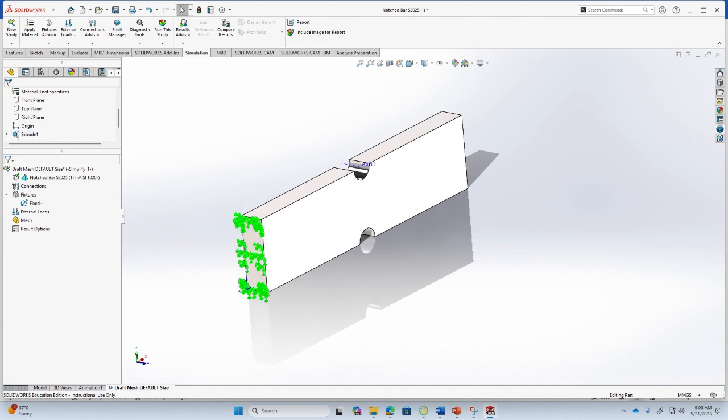And now these green arrows are showing you the constrained face, right? They are showing where the displacement is 0. So the way any finite element analysis applies these boundary conditions is that internally it writes this relationship F equals KU, where U is the displacement on each of the nodes of the elements, okay, and F is the force.